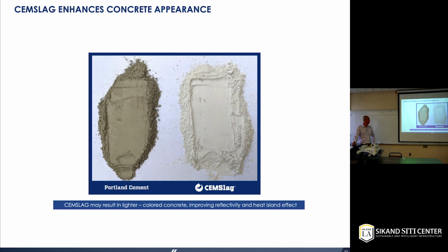And finally, here is the color comparison between the slag and the Portland cement. As you can see, it's a white powder. I'm sorry, by low temperature, what would be considered low temperature? Because at low temperature, when you're adding slag in your mix, it slows down the setting time. Yeah, we're talking about lower than 10 degrees C.